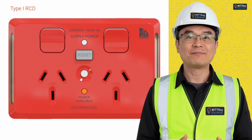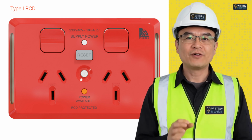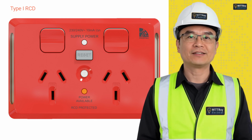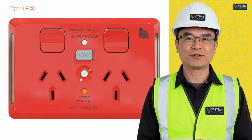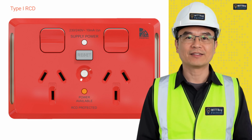But remember, 10 milliamps alone does not always prove it is Type 1. To confirm Type 1, we need the product information or marking to show it meets the Type 1 requirement, including the fast trip time. Type 1 RCDs are used for extra sensitive protection, especially in medical or patient areas. So this is a medical socket outlet with built-in Type 1 10 milliamp RCD protection.